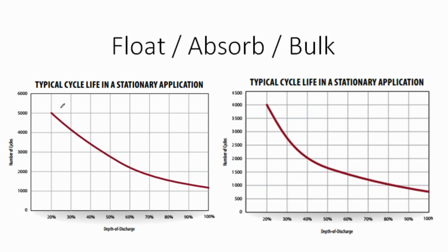And that gas you have to manage, you have to vent to the outside, but the flip side is the battery will be in better shape and it'll last a lot longer. And so the sealed batteries are marketed as zero maintenance, but it also means less life and higher cost, at least for upfront cost. So there's a purpose for a maintenance-free battery. But if you really want the cost effectiveness, you're going to have to do a little bit of maintenance.